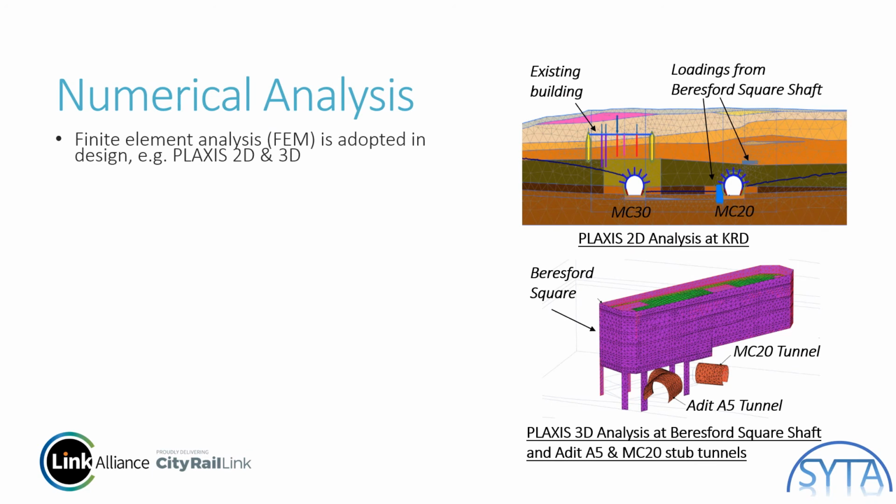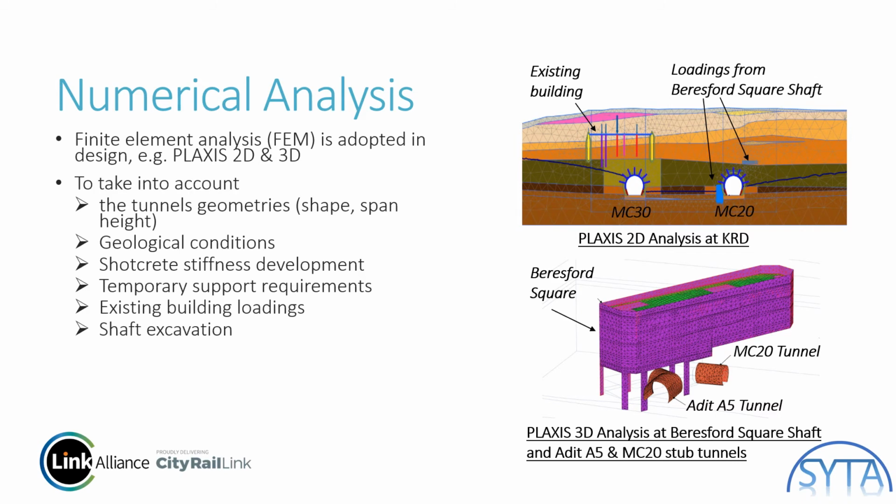Based on the input from the BIM model and the 3D geological models, we have carried out the temporary support design by using finite element analysis, such as the RS2 and RS3. Because we need to take into account the tunnel geometries, the geological conditions, shotcrete stiffness development, temporary support requirements, the existing building loadings, and the shaft excavation.